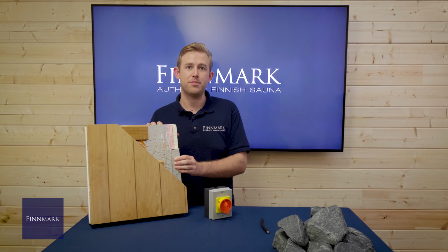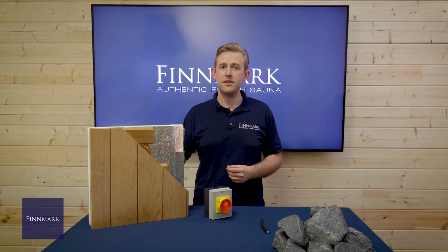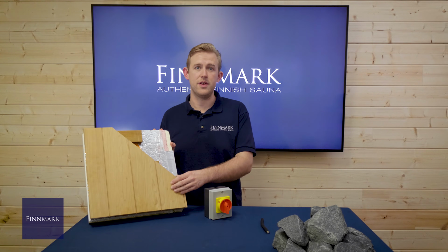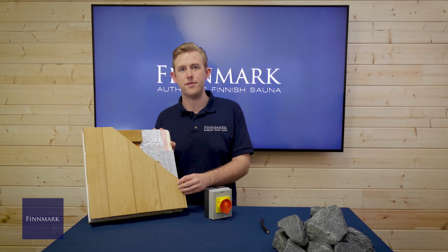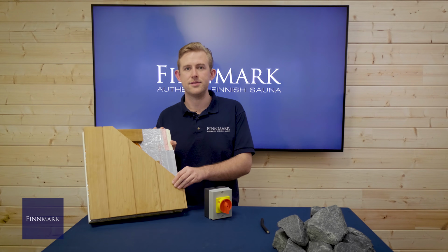The thermo-treated process turns a durability class 5 wood, in this case spruce, to a durability class 2 wood, which makes it far more durable and dimensionally stable, and less prone to warping and more resilient to condensation or moisture. We then secure the cladding to the battens. In this case, we've used Thermoaspen Callio profile. This cladding has been secured with stainless steel brad nails hidden within the groove side of the cladding.